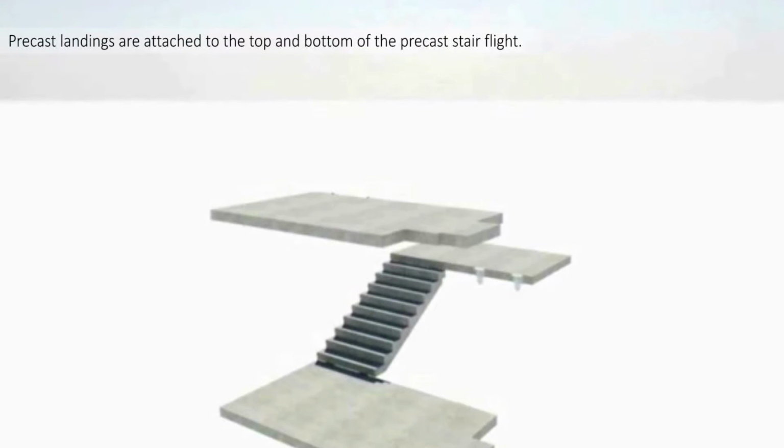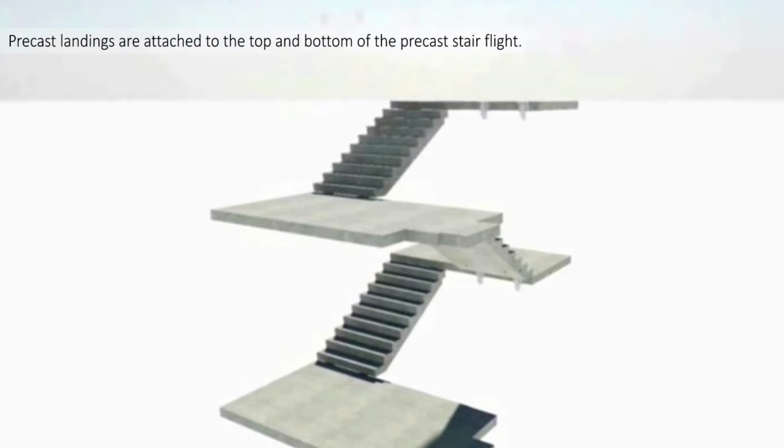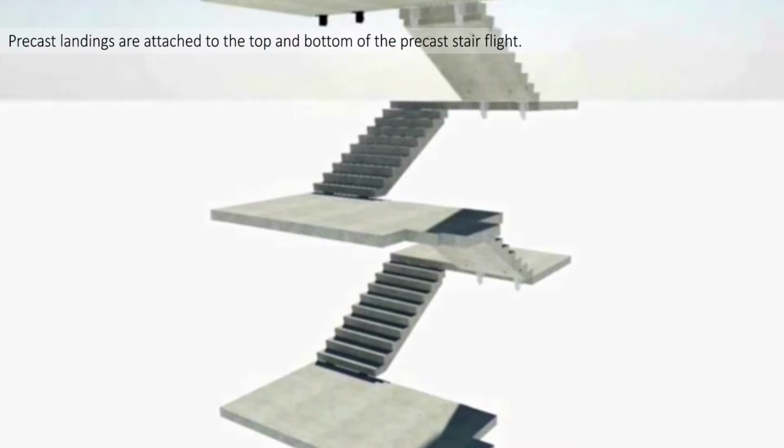Small concrete pads are set under each side of the steps toward the front of the unit. These pads are set slightly lower than the brackets so that the stairs are pitched forward for water runoff. The precast stairs are then set on the brackets and pads using a boom truck.